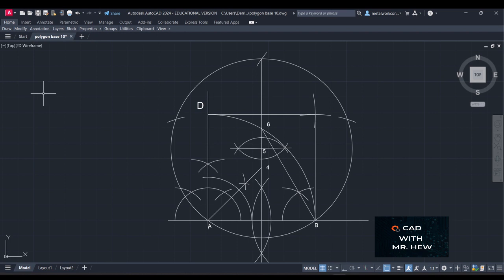All right. So what we have is arcs drawn from B, which is the length of the line AB, marked from B to give you this arc. Same radius from the intersection of this arc and this circle, you mark an arc to give you that point. Same radius, you mark another arc. Those arcs on the circle now will give us our pentagon. Good. So we go line at B, there, there, there, there. And that is our pentagon, right?